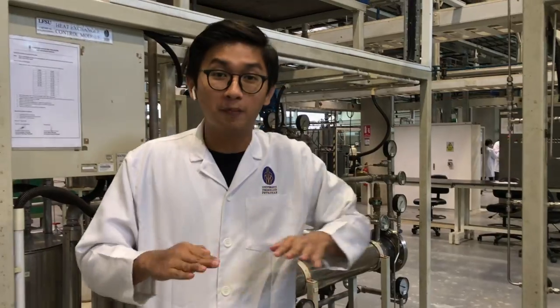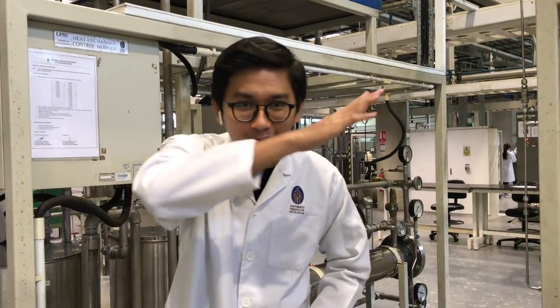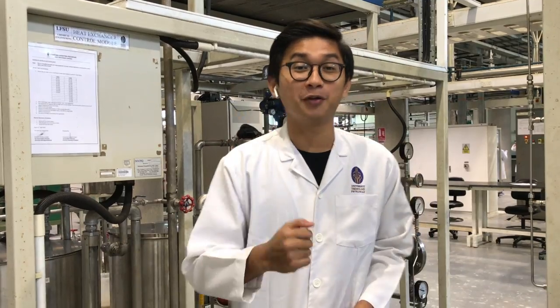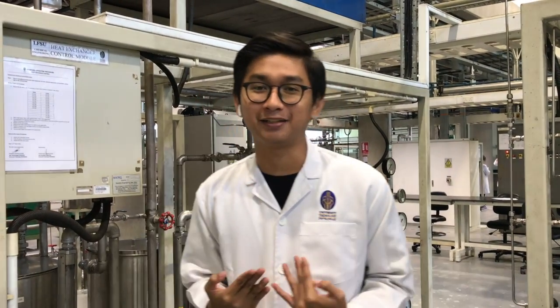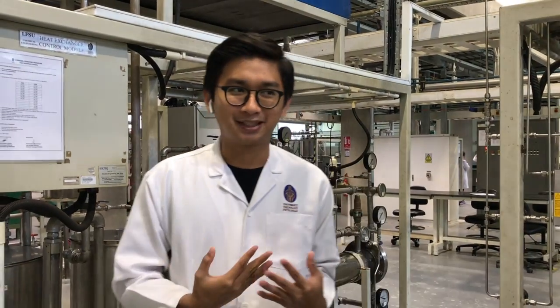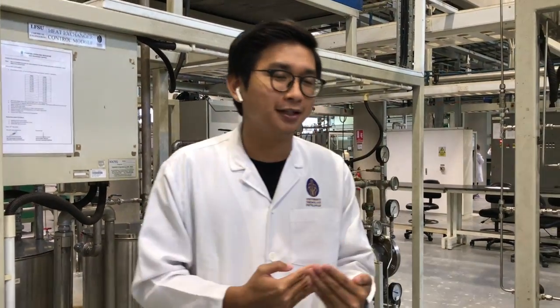For your information, the P controller will reduce the offset, but it won't reach the set point at all. Next, the PI controller will eliminate the offset, so there will be no offset, but it will produce oscillation. And lastly, the PID controller will eliminate the offset and reduce the oscillation. As a result, PID is the best controller compared to P and PI, because we can get an accurate result and reach the set point faster.